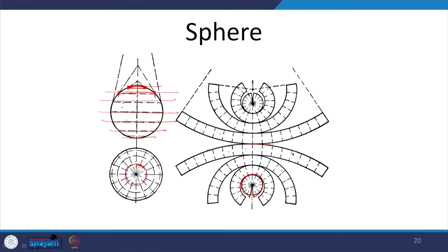This circumference is different from the circumference which we would actually see from the top. So some portion will be cut and left. Similarly for the others, there will be different circumferences. This circumference is equal to this, but this one is arrived at using this diameter. Likewise, we keep opening up the horizontal strips of the sphere, and then we can join all of them together to give another approximate shape of the sphere.